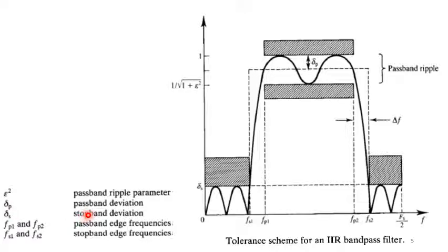I think you are familiar with these notations: sigma of p represents the passband deviation, and this new parameter, delta, represents the passband ripple parameter, which is the difference between the minimum and maximum deviation in the passband. We have the stop band deviation represented by sigma of s. This is the same as what we had in the case of FIR systems.